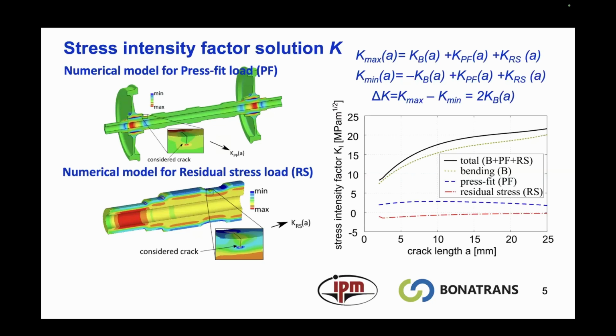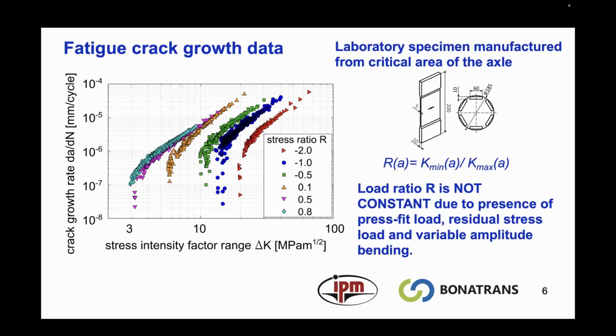We consider residual stresses due to manufacturing processes, for example, due to technological processes such as hardening of the axle, and so on. For our calculations, we usually use the stress intensity factor as a quantity describing the stress concentration in front of the crack tip.